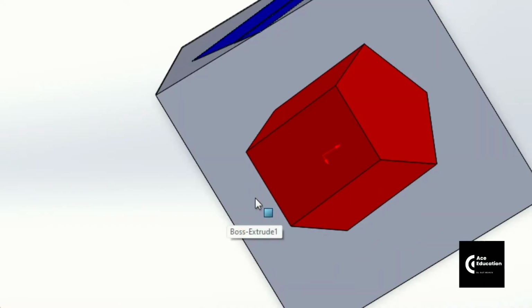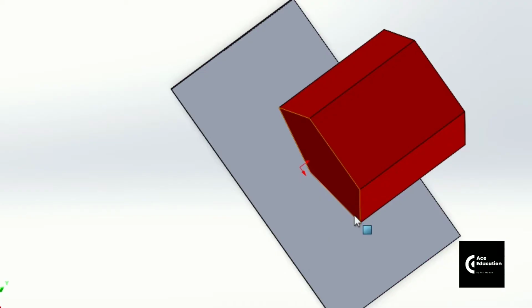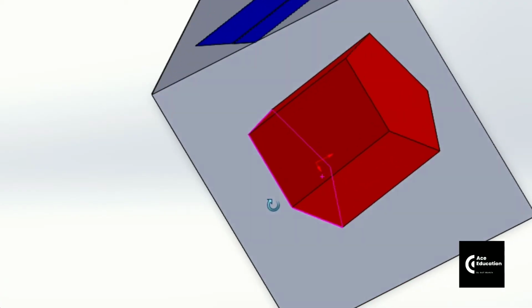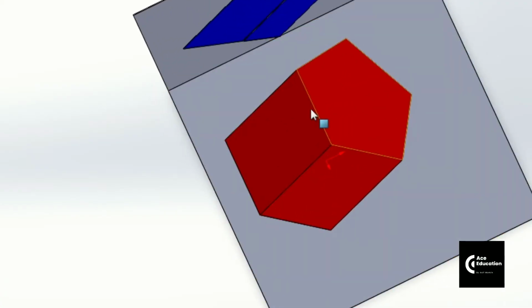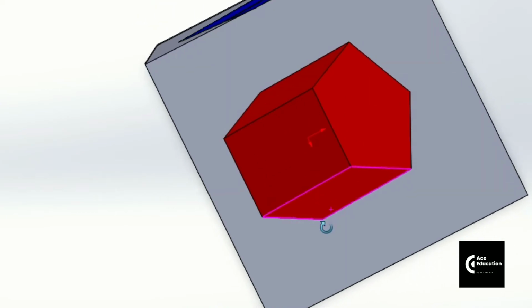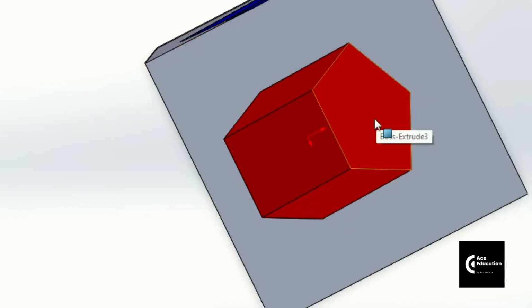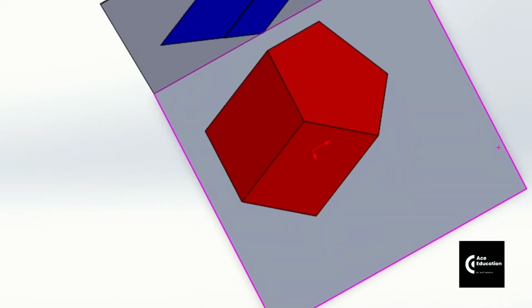But when you are trying to observe the lower base of the solid, only 3 edges of that base can be observed. The other 2 edges, which are beyond objects, can be drawn as hidden lines from the top. Because this base is nearer to the observer, the other base would be away from the observer. So the remaining edges of that solid will become hidden lines. Also, the vertical edge which starts from this corner point beyond that surface will also become a hidden line. This way you can complete the second stage.